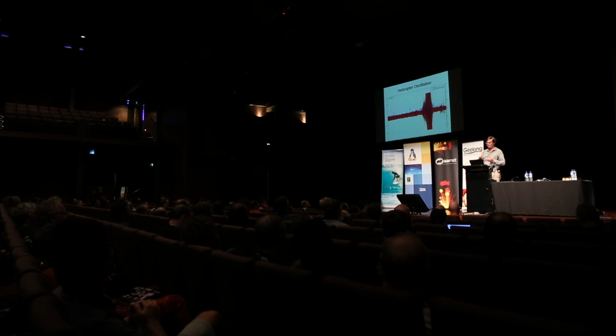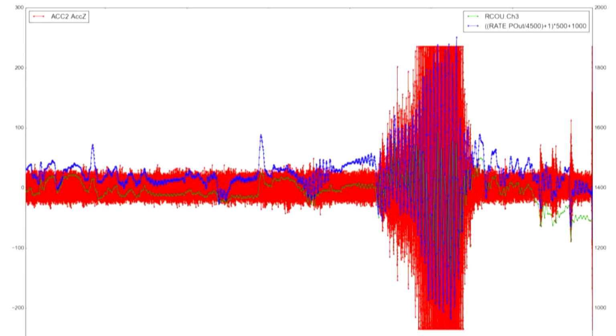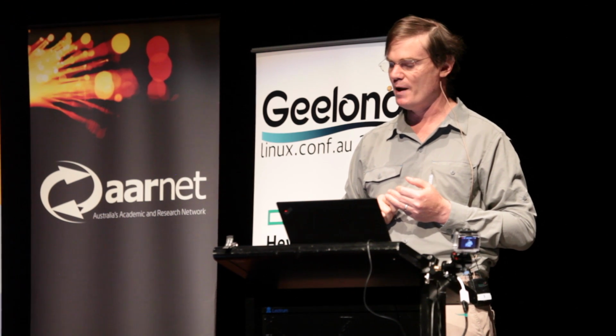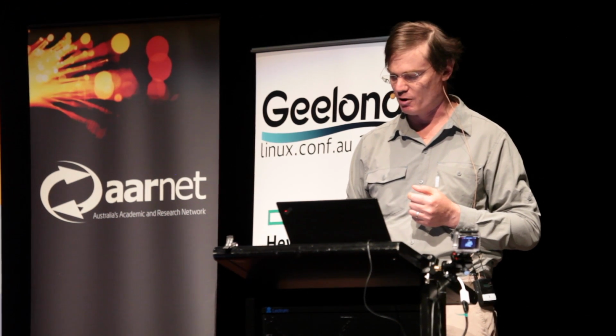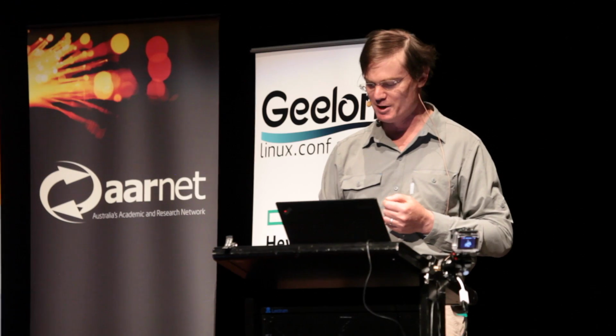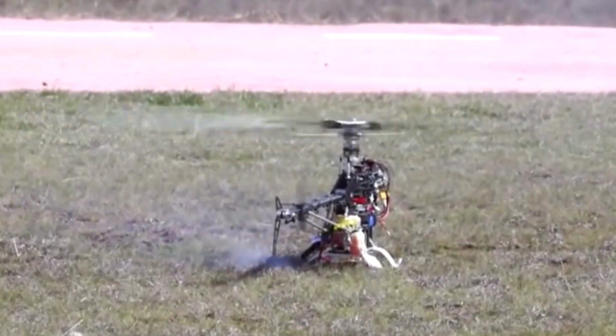And we actually dropped the tuning factor down. You can see that it did recover in terms of oscillation, but by that stage, it had lost the plot as far as the attitude of the aircraft was concerned, and it was no longer controllable. And when they go wrong, they go very badly wrong. But when they go right, they're wonderful. So here's one going right.